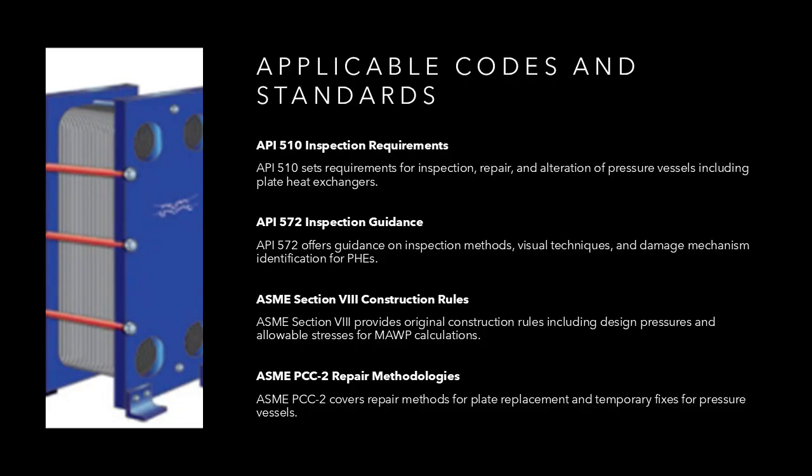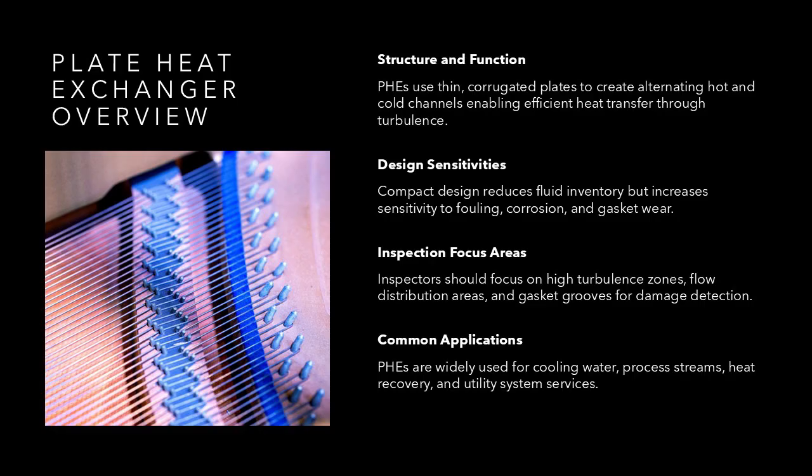ASME Section 8 provides the original construction rules, including design pressures, temperatures, and allowable stresses that underpin MAWP calculations. ASME PCC-2 may be referenced for repair methodologies when plate replacement or temporary repairs are considered. Inspectors must understand how these documents interact and apply professional judgment when adapting general pressure vessel requirements to the specific design features of PHEs. This slide provides a technical overview of plate heat exchangers from an inspection standpoint.